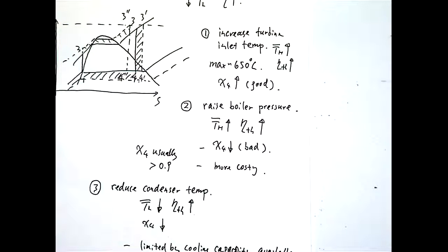One practical problem is the container is not perfectly insulated. The more vacuum it operates under, the more likely it will leak, right? Any small crack, which is fine in a low vacuum condition, will start to leak in a high vacuum condition. And when air leaks into the system, is that okay or not? Air cannot cause an explosion in the process, since you don't have fuel involved, but the air is not part of the water or the steam.